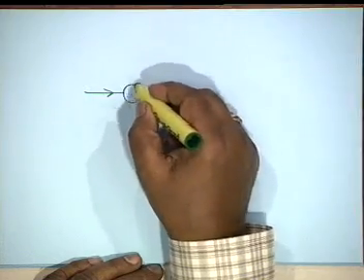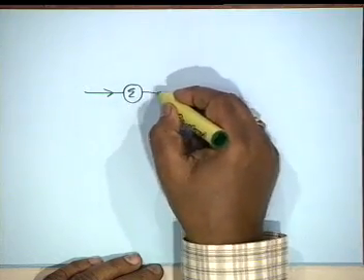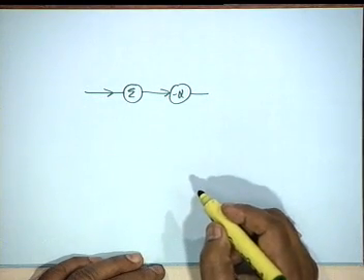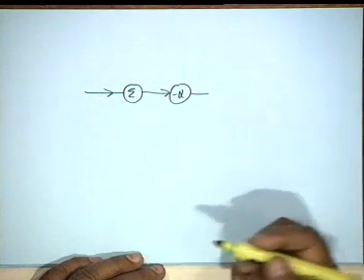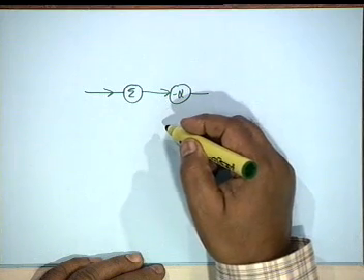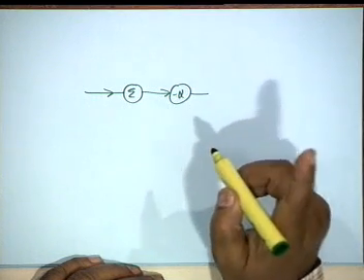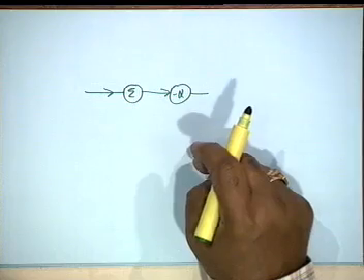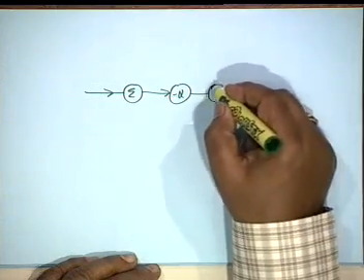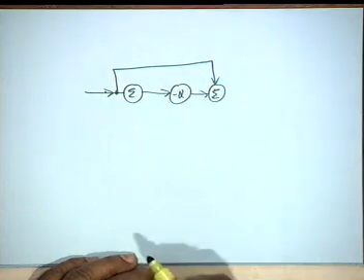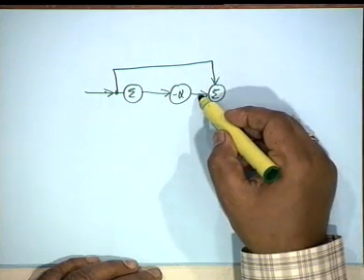The structure is, let me draw it. I shall not draw it later. When I require to draw a lattice, I will simply put it in a box and put the reflection, the k, the lattice parameter. Lattice parameter here is minus alpha. You remember, in the denominator both of them have 1 minus alpha z inverse. So, the lattice parameter is minus alpha, then you have a summer, and the input comes here.